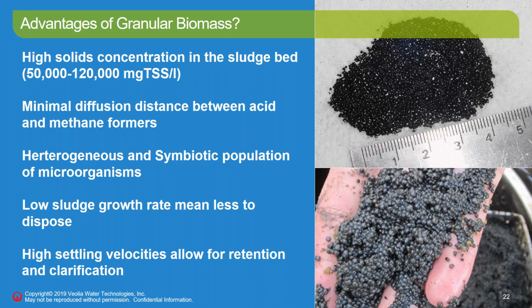Also, we get low sludge growth rates, which means that you have a lot less to dispose of. And again, the high settling velocities allow for retention and easy clarification. Very, very important in these high rate systems.